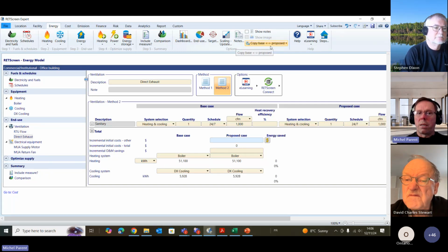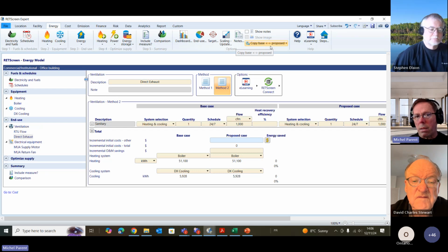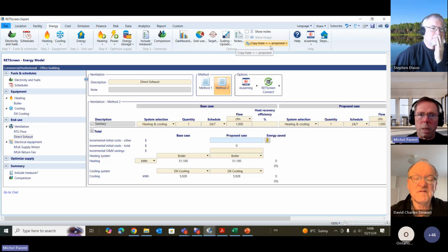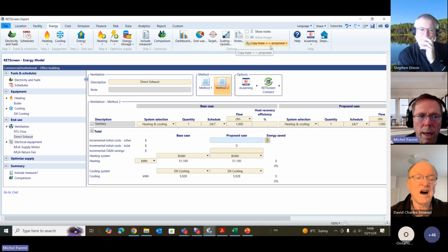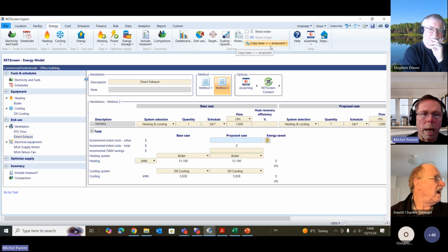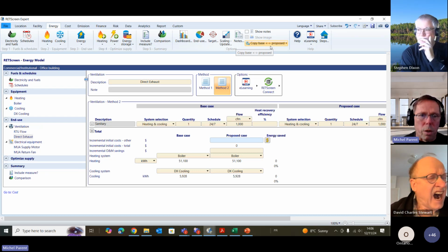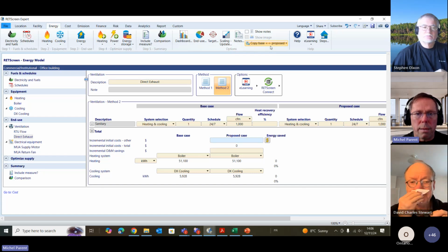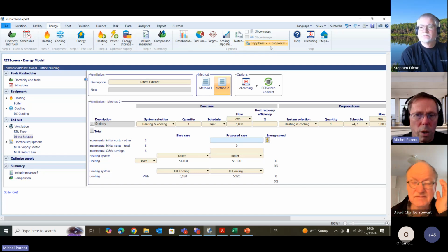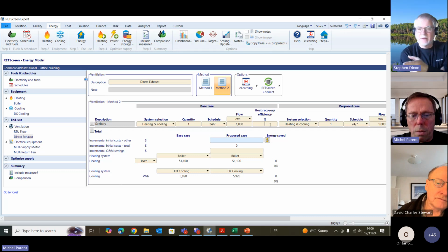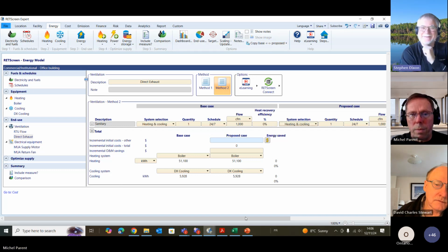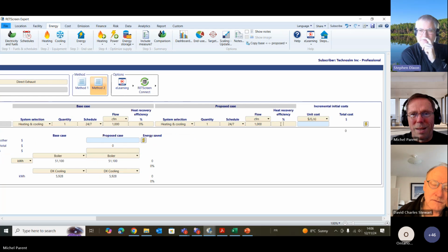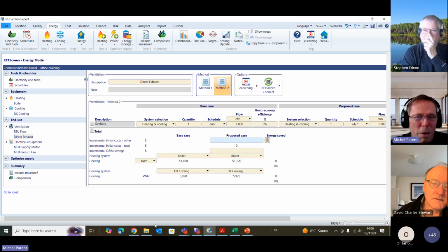Now you define your exhaust flow. And like I said before, that exhaust in RETScreen is automatically compensated with the equivalent amount of fresh air coming in. That's why we did not define it in the rooftop unit. It will not go and take 1,000 out of the rooftop unit. So you would end up with 2,500 CFM of outside air in that section of the building, or for a given building, for that building. Just in case anybody's wondering, leaving a blank or a 0 is the same thing on heat recovery efficiency. Yeah, but it's good practice to enter it. Oh, I was just about to do it.